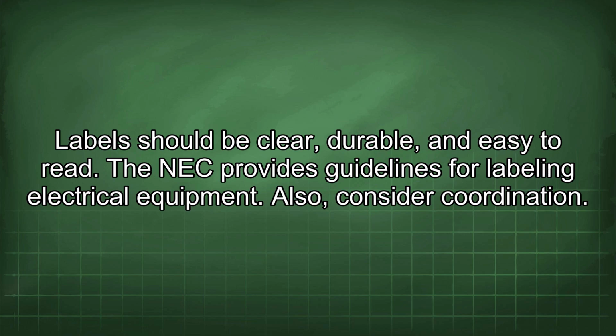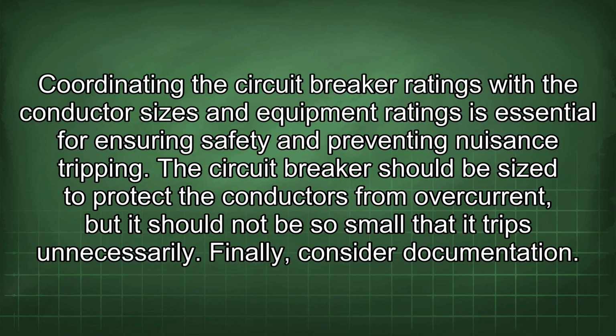Also, consider coordination. Coordinating the circuit breaker ratings with the conductor sizes and equipment ratings is essential for ensuring safety and preventing nuisance tripping. The circuit breaker should be sized to protect the conductors from overcurrent, but it should not be so small that it trips unnecessarily.